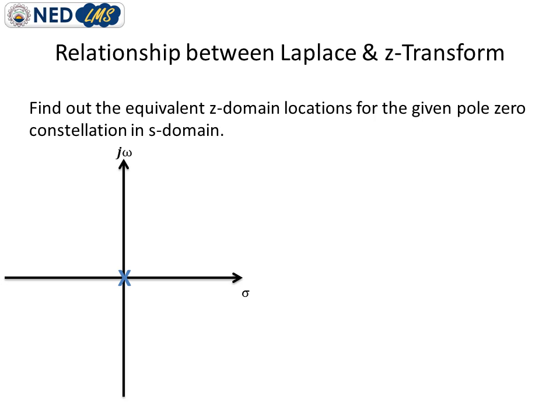Now here we are provided with a single pole lying exactly at the origin. We have to determine its equivalent Z domain location, that is, where this pole actually lies in the Z plane. We know that for this particular position, which is the origin, sigma is equal to 0 as well as omega is equal to 0.